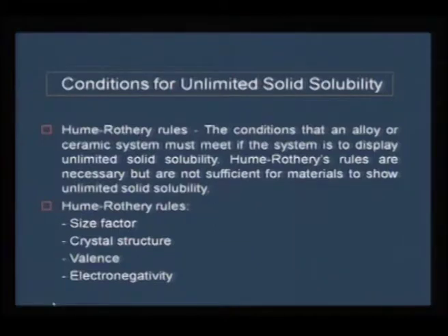So, there are conditions for unlimited solid solubility, and the Hume-Rothery rule is one guiding principle which will tell us how much solid solution capability can be achieved between two metals. The rule suggests that size factor, the corresponding parent crystal structure, valence and electronegativity, all these play an important role in fine tuning a solid solution.